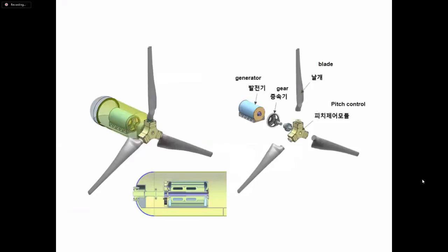So for wind power, when a typhoon is coming, the blade can be broken because of the high wind. So they want to escape, so they use rotation. The angle of attack is lowered to minimize the wind power. This time, this is current power, so water instead of wind, right? Same logic. They want to control the pitch to protect the blade.